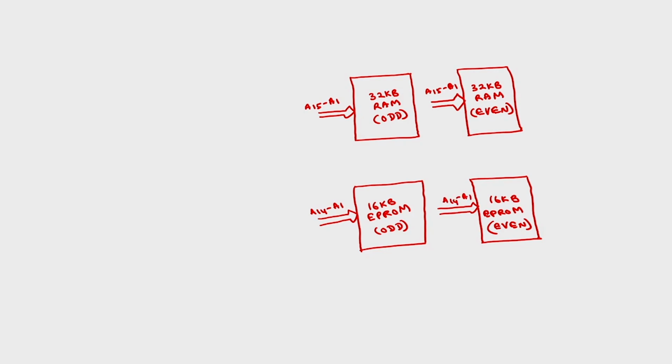So all the 4 buses you are going to connect to the common bus of 8086. Now the question is, how will these 4 devices be differentiated? At any time only one of these memories will be selected, so the data transfer will take place with that particular memory. Even though the common bus of 8086 is connected to all the 4 memories, at any time only one memory is selected, so that the data transfer takes place with the selected memory.